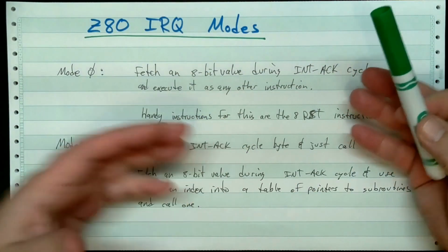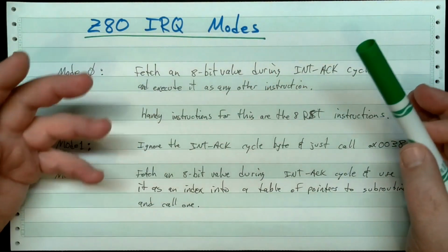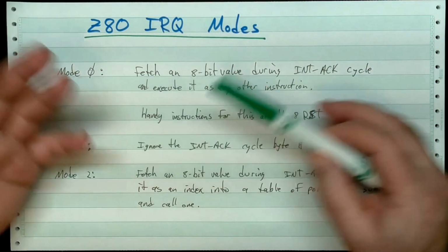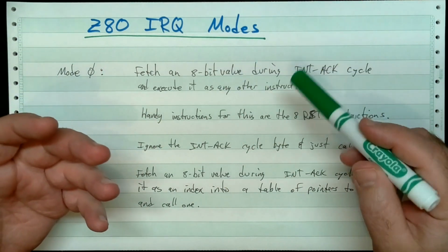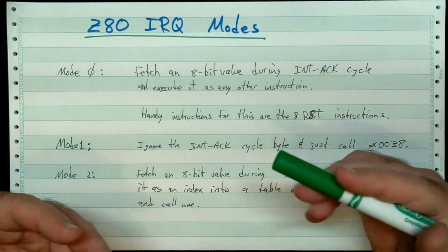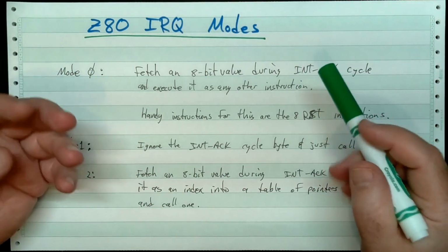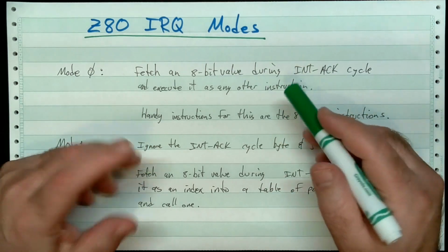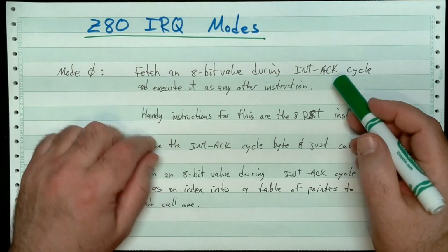That way the software can work as is pretty much. You just take the firmware from an 8080, you build a new product, you don't want to use the 8080 anymore, you move on to the Z80, which is a lot easier to work with. I mean, it runs on 5 volts only. You can get them to run on faster clock speeds, and the clock signal itself is less complex. I'll let you Google that to get the details if you want.